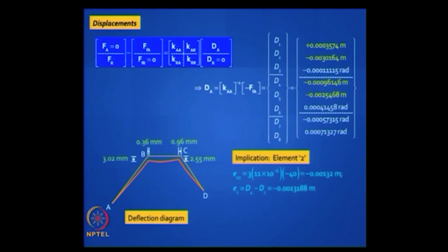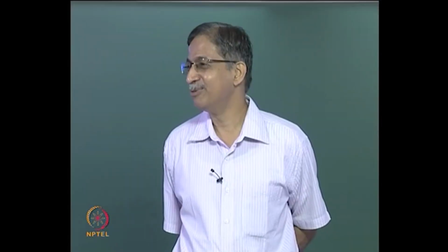So close that if you multiply the element stiffness EA by L by that and add the fixed end force, plus 990 minus 989.1, ladies and gentlemen, the force is less than 1 kilonewton. This is really beautiful, right?